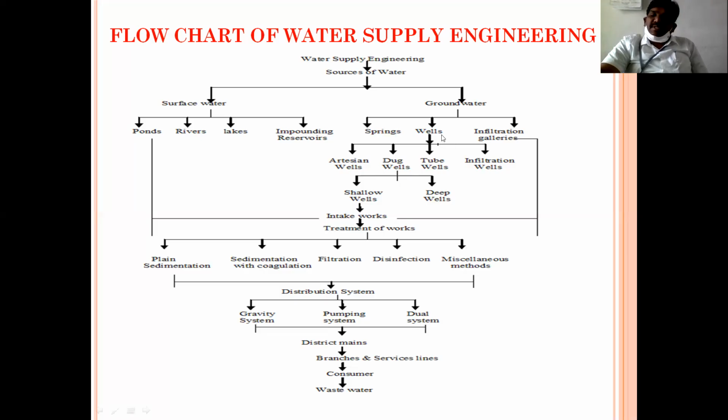What is the purpose of these wells? I mean, the purpose of a well is to get the water, or to meet the requirement of water. What is the requirement of water for a human being? That is 135 liters per day. We have seen a clear bifurcation of that 135 liters for various activities like cooking, drinking, bathing, so on. See here, when the required discharge is minimum, we may go for wells. And for individual purposes, in the same wells, we have seen 3 types of categories.